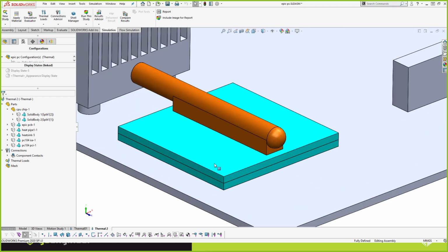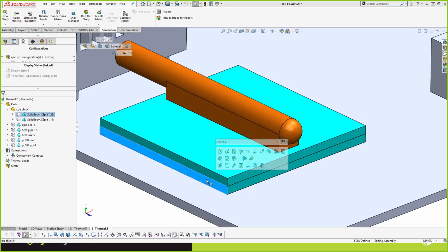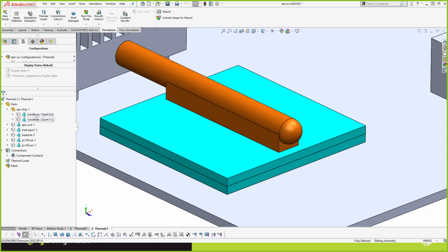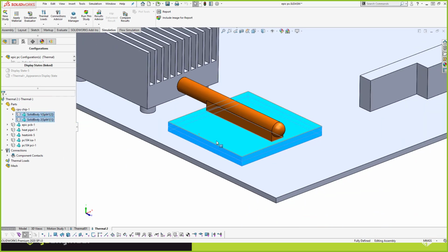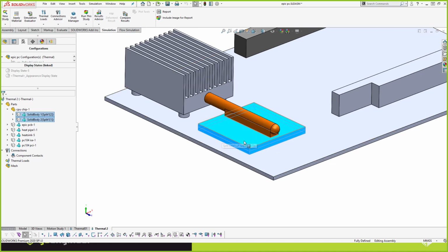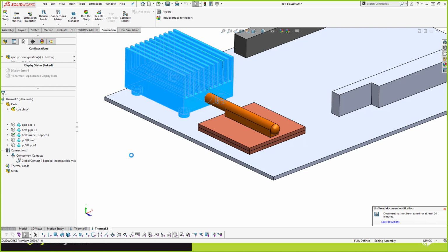I've got my heat chip modeled as two bodies, one for the junction and one for the case. I'll just use a high conductivity body for those, since I'm not actually modeling the chip perfectly accurately. I'm just going to be modeling it with thermal resistances in a moment. So I'll go ahead and use a high conductivity material for those two. I'll just use copper or something. Now the heatsink is made out of copper, so that one I will also use that copper conductivity for.